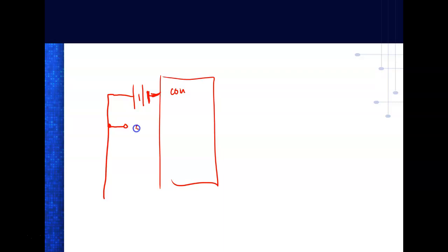So I've got a normally closed push button, which is supposed to be a stop, so that's my stop. And here we're supposed to use the actual electrical symbol. And then I've got this running into input 0/0, and then I've got the normally open running into input 0/1. Now on your switches, they're just labeled 0, 1, 2, 3, 4, 5, like that.